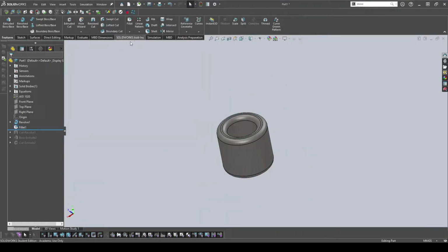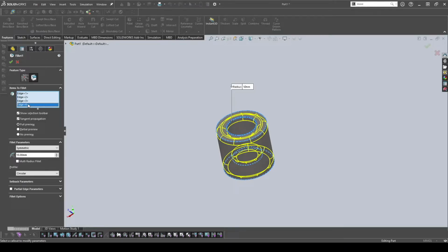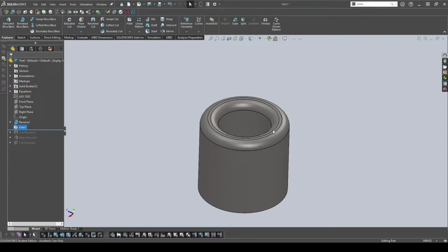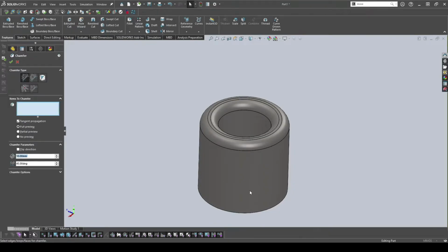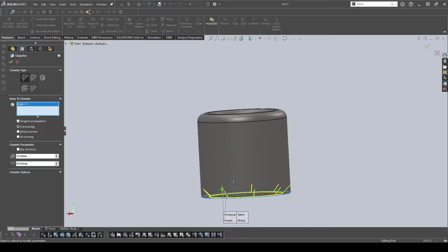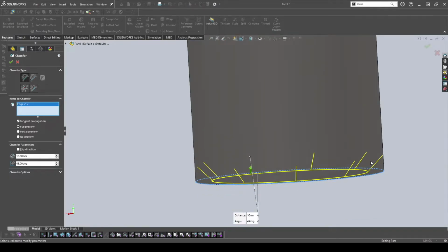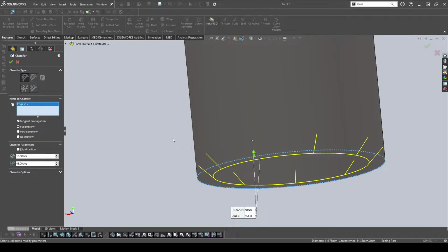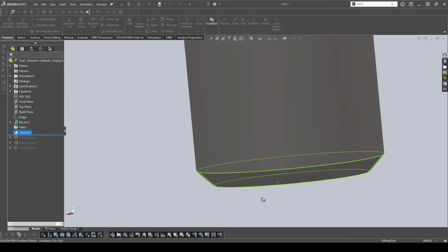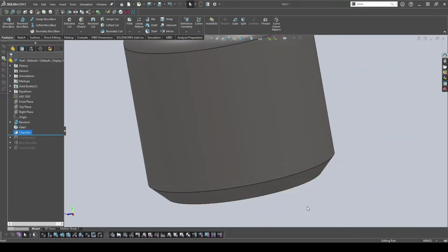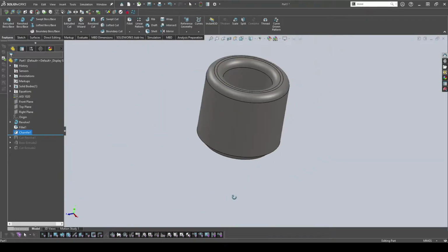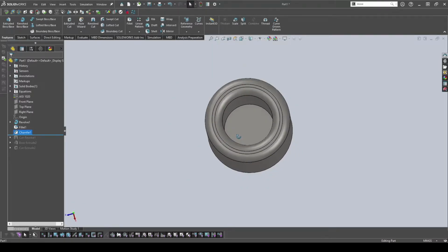There's also a different feature, so if you don't want round, but sharp triangled edges, so if I delete those two, keep that round, I can choose the chamfer tool here. Basically, the chamfer tool gives you a more hard edge, so it removes the original sharp edge, but it gives you a more triangular edge there. So just a little different type of edge that you could add onto your parts.